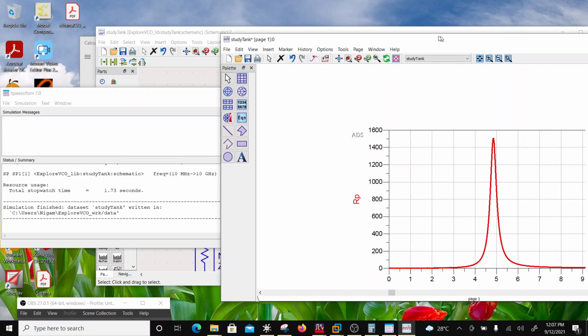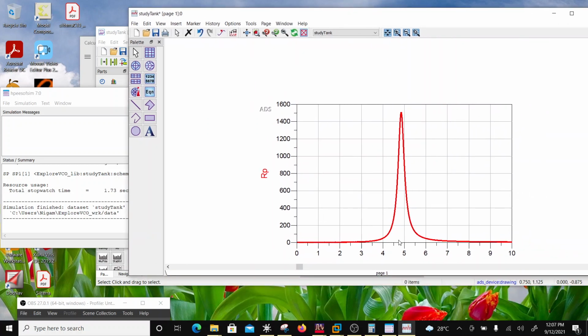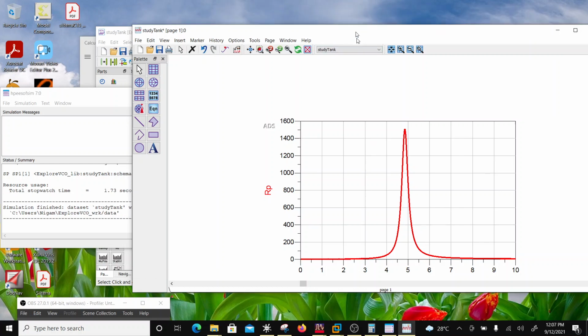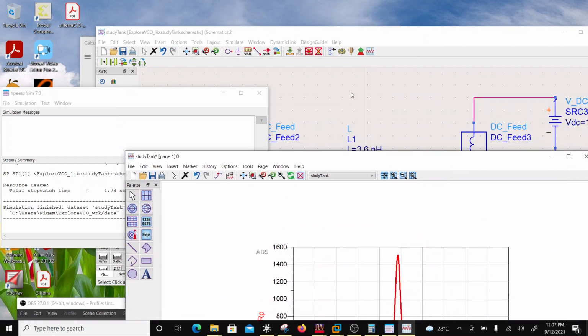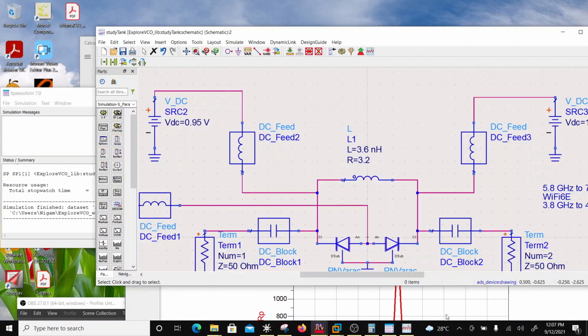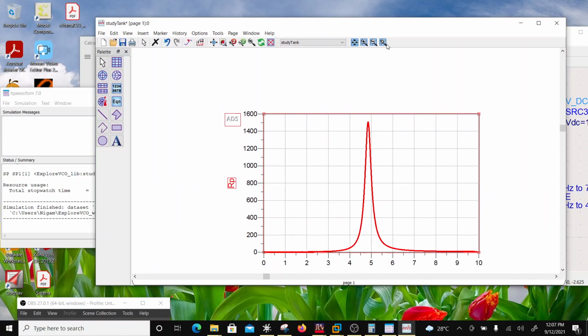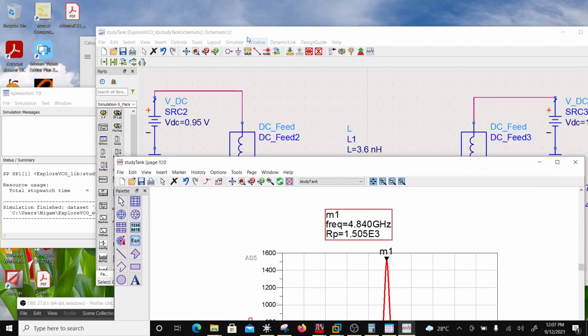Okay, so now we are in the range of sub 5 gigahertz. We have to go from 3 point something to 3.8 to 4.8, right? Now let's target 4.8, right? So are we at 4.8 right now? Yeah, so we are at 4.8 roughly. Marker new, 4.8 gigahertz. Now let's see if I change the control voltage, what's going to happen.